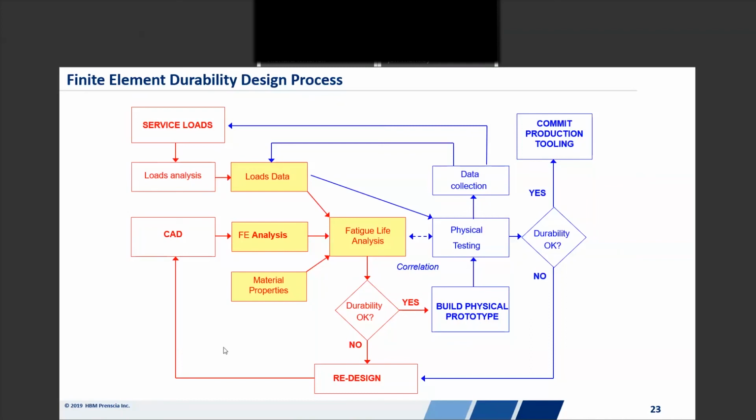The key here is we're doing much of the design for fatigue up front, and that's critical because fatigue tests are expensive. I actually have to have a part to test. They can also be extremely long. Think about this. I have to go off and use the loading that my part's going to see over its entire lifetime. Those tests may run weeks or months. And putting that long duration test in sequence with a design process just stretches out the design.